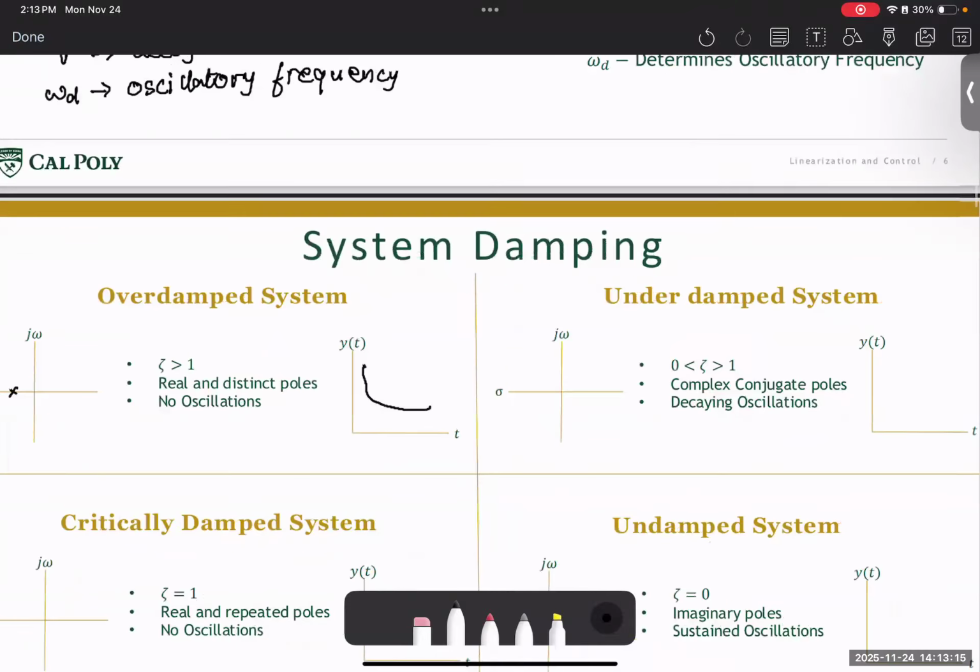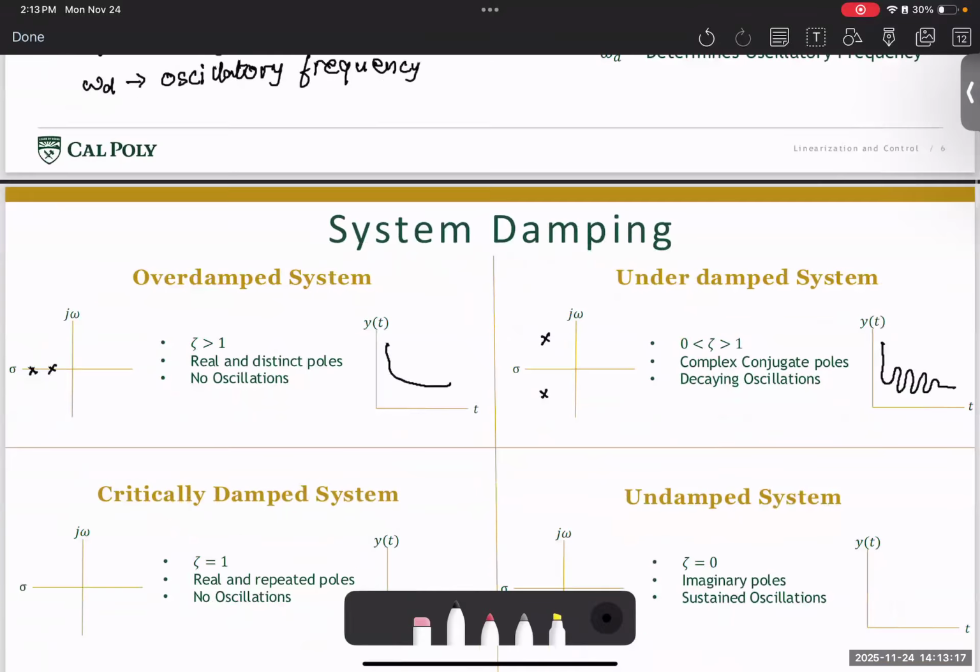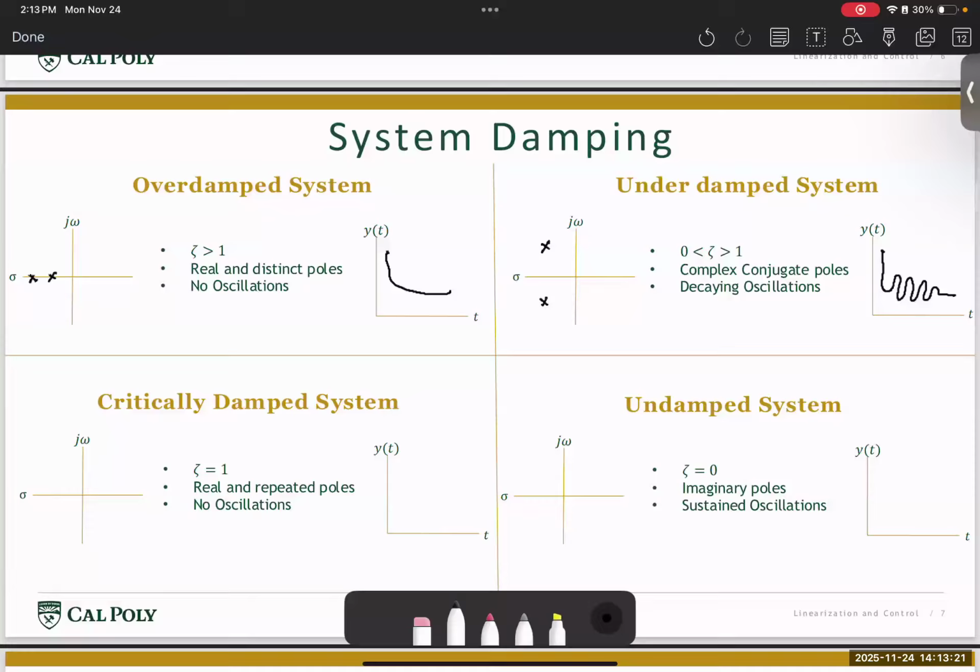And such a system is also called an underdamped system, because once you provide a control input, the system takes some amount of time and creates some amount of oscillation before it ends up in its final state. While in the first case, when zeta is greater than 1, we say that the system is overdamped, where we're providing a lot of control for the time constant and the damping coefficient or the damping frequency of the system, which causes it to settle smoothly.